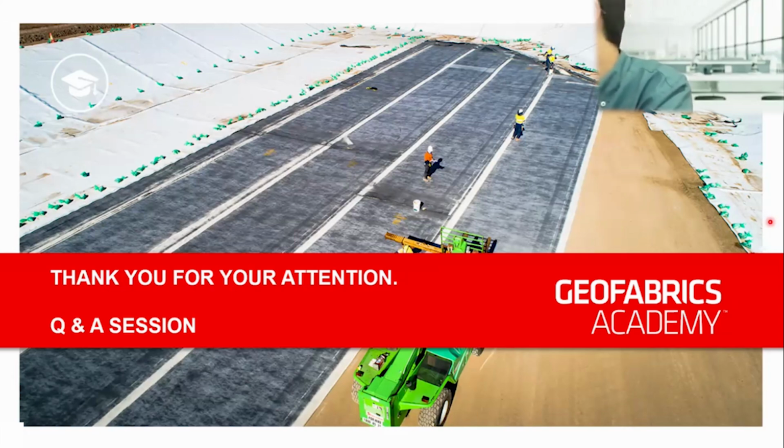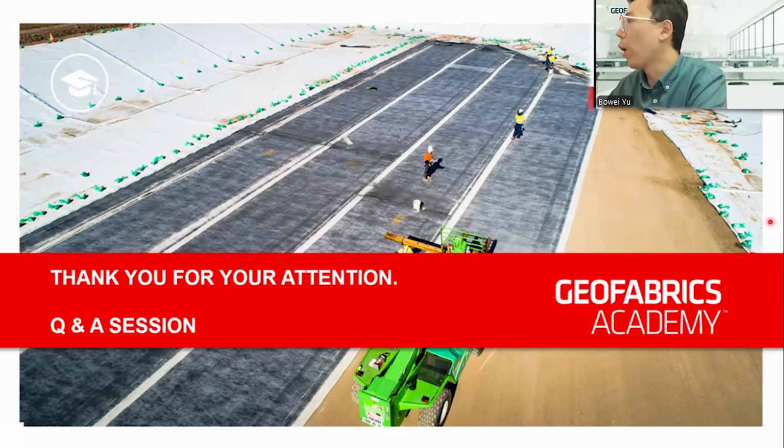But for some other material, like the geomembrane, it's probably less sensitive to that. But again, it really depends on the condition, whether you have those aggressive chemical environments, or at the same time, you probably also have some elevated temperature. So it can be quite site specific. I reckon in certain cases, it's better to carry out some actual tests to validate that it is suitable for your specific site conditions. Right.